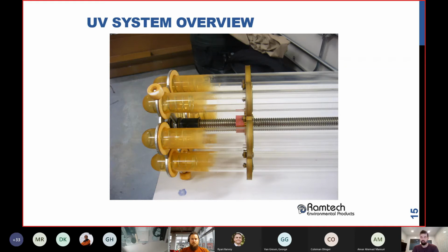That's cleaning it; you can change the interval, but probably every hour or so. And on the left, that's the very end of the sleeves where the lamps are not located, and that's not cleaned. So you can see how effective a wiping system is. And if you don't take into consideration what fouling can happen when you design a plant, this is what you can end up with. It can really impact the amount of UV intensity that gets out into your water.